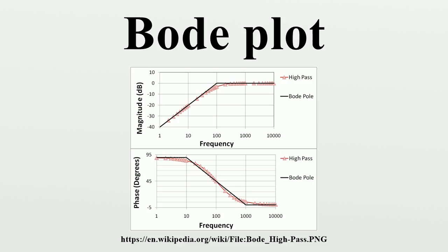Figure 2 shows a Bode magnitude plot for a zero and a low-pass pole, and compares the two with the Bode straight-line plots. The straight-line plots are horizontal up to the pole location and then drop at 20 decibels per decade. The second, Figure 3, does the same for the phase. The phase plots are horizontal up to a frequency factor of 10 below the pole location and then drop at 45 degrees per decade, until the frequency is 10 times higher than the pole location. The plots then are again horizontal at higher frequencies at a final, total phase change of 90 degrees.